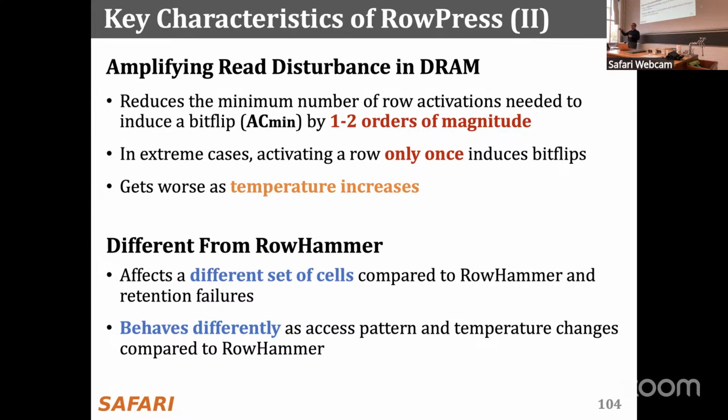I mean, we looked at the effect of temperature on the RowHammer and row press bit flips if you keep the temperature constant. But how much effect does hammering have on temperature? I'm not sure. It becomes a bigger problem on HBM. In DDR4, it's very hard to increase temperature, actually. But HBM, because you're 3D stacked at the memory layers, the heat cannot escape anywhere, right? And cooling may not kick in as quickly. So there could be some temperature increase. That's a good question. Maybe you can study that with the infrastructure.